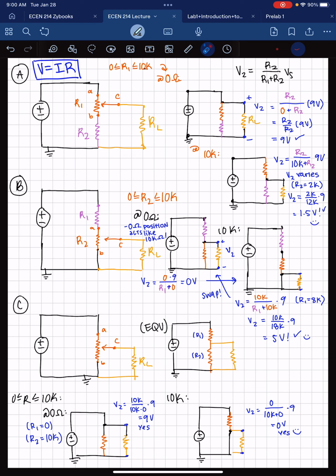So do you remember in lab when it was the 100 ohm resistor, it would drop and it would be something in the millivolt range, and it was really small. And then when we measured it with the 100K ohm resistor, it was almost like if you had 5 volts between here and here without a load, then it was almost 5 volts with a really high resistance.